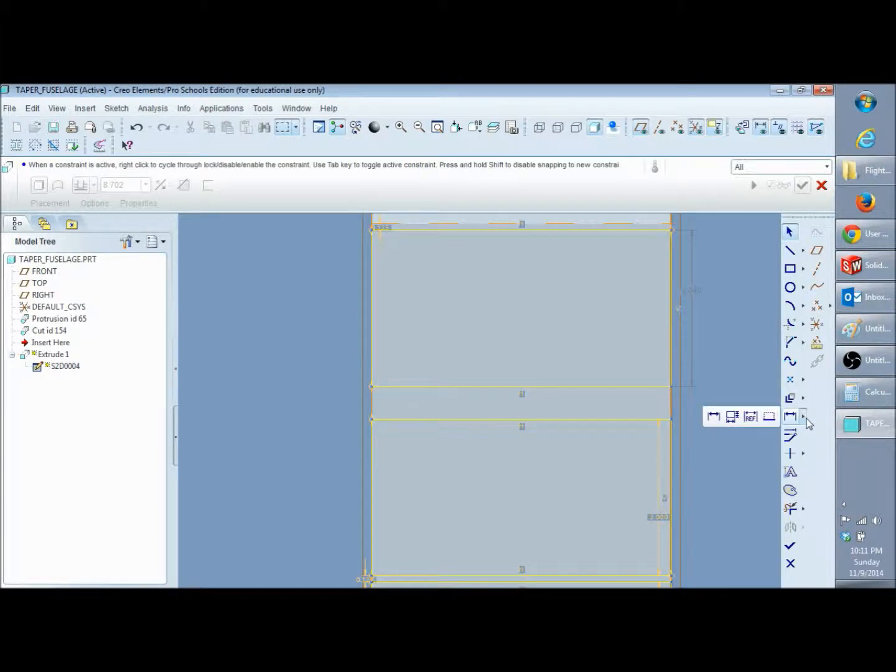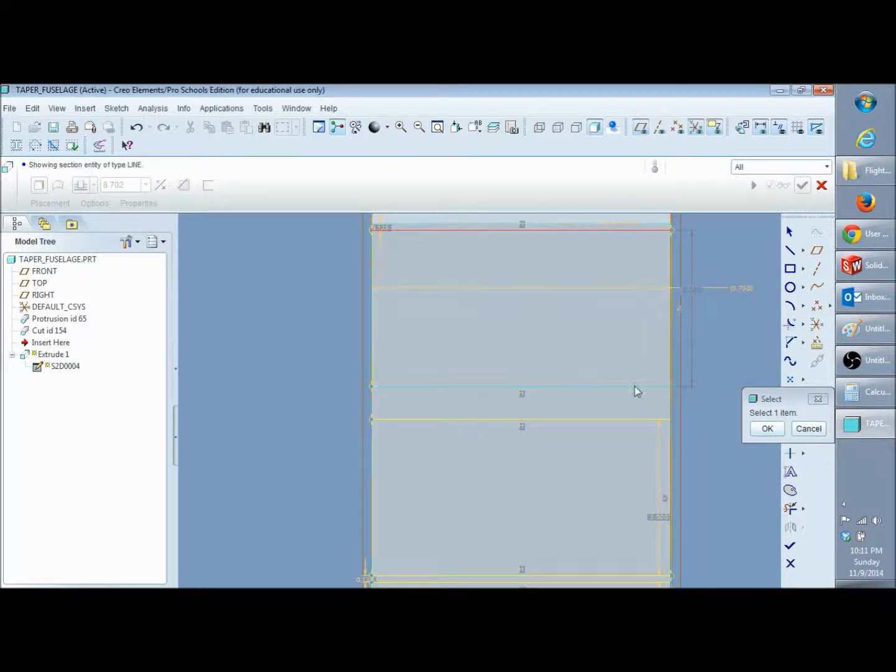Where's the dimensions tool? Okay, I'm gonna create a reference dimension between these two. Wait, no. Okay, click. Okay, there you go. 3 inches there. Whereas I want to create an actual dimension between these two. The reason why is that you cannot over-dimension your drawing when you're creating your shape.